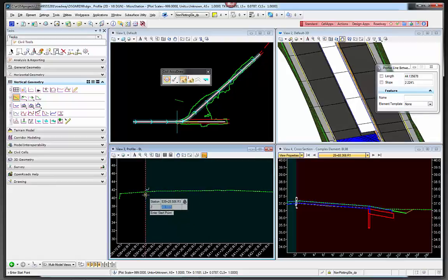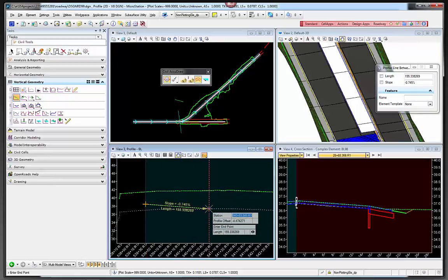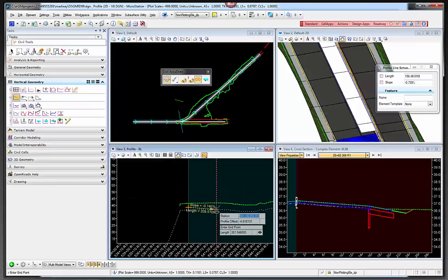And then if you want to be offset from the existing ground, you can set the profile Civil AccuDraw offset. If you tab to the offset field and hit the O key, it lets you pick a reference line to be offset from. And then you can lock it to, say, -3 feet below there. And now I've set a point right there at that location. So the first point is now on that PC, 3 foot offset from the existing ground. I did that all by using the profile view and Civil AccuDraw.